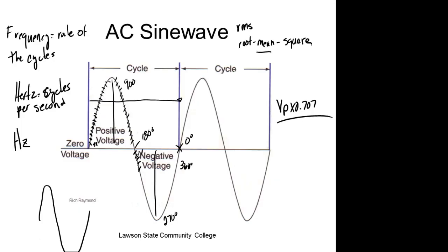So all I've got to do is take coils out here and spin them. If I offset the coils by 120 electrical degrees and put 3 wires on, I get 3-phase. 3-phase generators cost more, but we save it back by being more efficient for transmitting power, right? We get 73% more power transmitted for just adding 1 more wire. But when I get down to my low power loads, like my house, it would be more expensive to run the extra wire out there, because now I've got to have 3 transformers on the pole instead of what? Instead of 1.